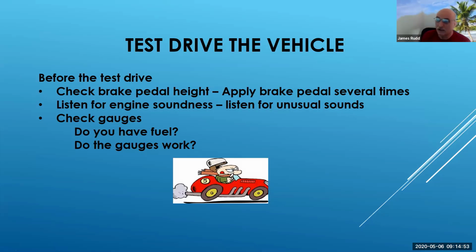All right, so then we go into the test drive, folks. One of the things I do before a test drive is check the pedal height of the brakes. I do not want to hit that wall. I've had a few occasions where this really gets scary when the pedal fades. If I get a customer complaint that the pedal fades, it's not going for a test drive. I am definitely checking all points of that brake system before I even go anywhere.